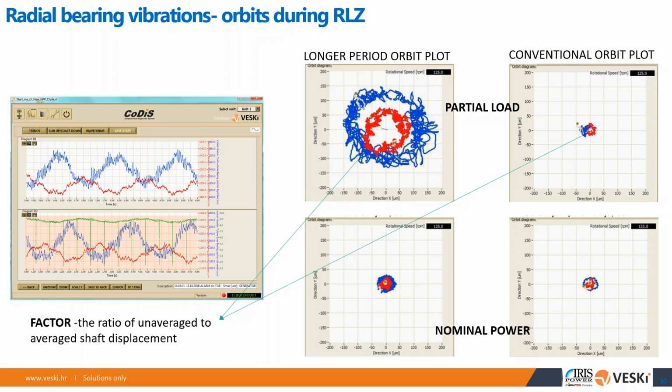Next question. Where should one measure axial displacement exactly? One measurement should be on the turbine cover. This will give you basically the lift of the turbine cover relative to the concrete foundations. So you're measuring from the concrete foundations to the turbine cover, and then another one should be on a bracket measuring the oil film. Basically we're trying to figure out if there is a lift of the rotor to the bearing, which creates the oil instability.